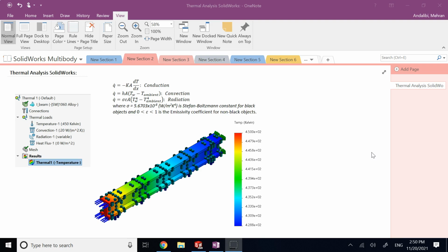So for example, you can try to have a heat sink or a heat source element within the object, which is not super realistic most of the time, especially if it's a solid object like this. If it's like a room or something, yes, but the other modes of temperature and heat transfer that you can consider is if you can keep the temperature on an edge or a wall or surface or something like that constant. If you can consider conduction, which happens almost all the times, right?